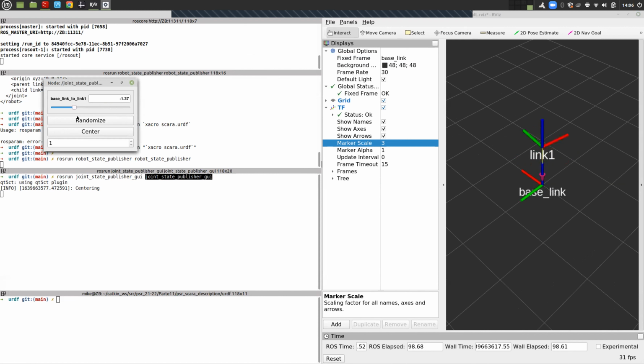Okay, so that's the first part, is to have all this pipeline working and well understood, because this is going to be the core of many things to come. What Jose showed at the beginning of class was a bit more than this, but it was just an addition to this basic concept of having someone publishing joint states, so angles, which are then interpreted or received by the robot state publisher that computes the direct kinematic and publishes transformations. Because now, if my coordinate systems are being positioned somewhere in space because of the transformations, now I can draw stuff attached to these reference frames, okay?